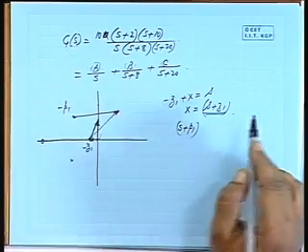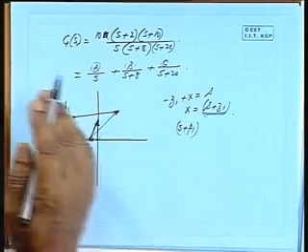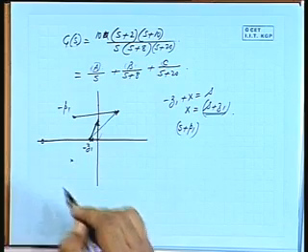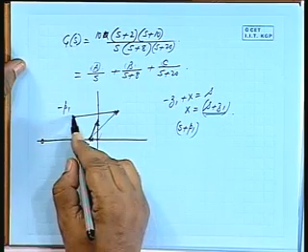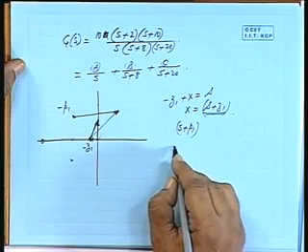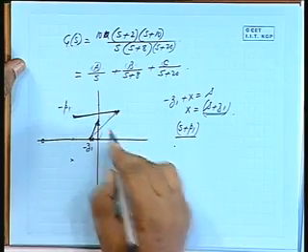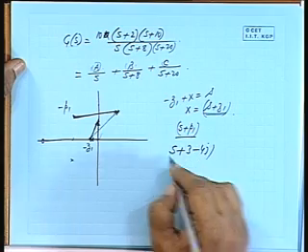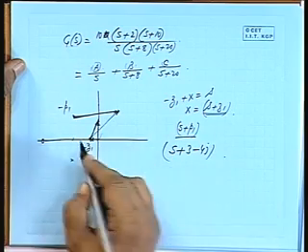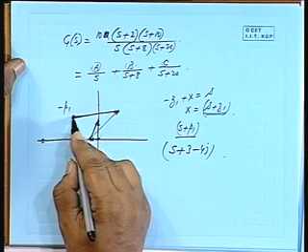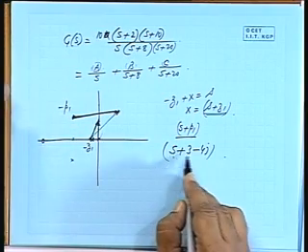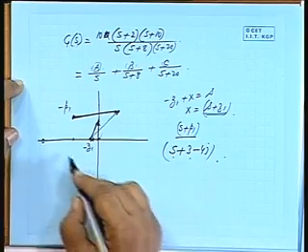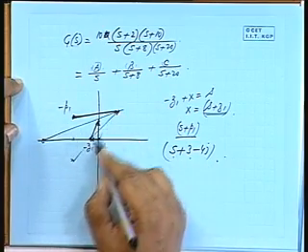If S plus P1 is a factor, then S equal to minus P1 is the root, all right. So, if this is minus 3 plus 4j, then the factor corresponding to this vector will be S plus 3 minus 4j. If minus 3 plus 4j is this point, then this vector is S plus 3 minus 4j. Okay. Similarly, for this one and so on.